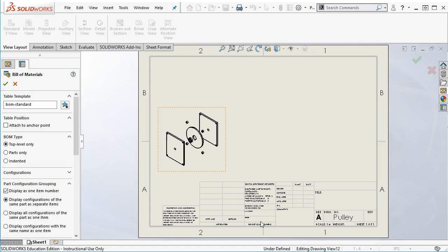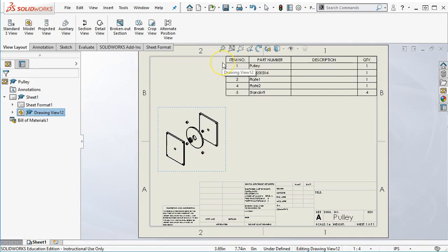If you look at one of my detail packages, typically it's going to be pick this part up first, turn the page, pick that part up, and those two parts go together. All right, I can't always achieve that, but a lot of times that is at least the intent. So a bill of materials standard is going to have a couple extra columns that I won't need. And this can be top level only because there's not sub and sub-sub assemblies or anything like that. And again, keep in mind this is the optional side.